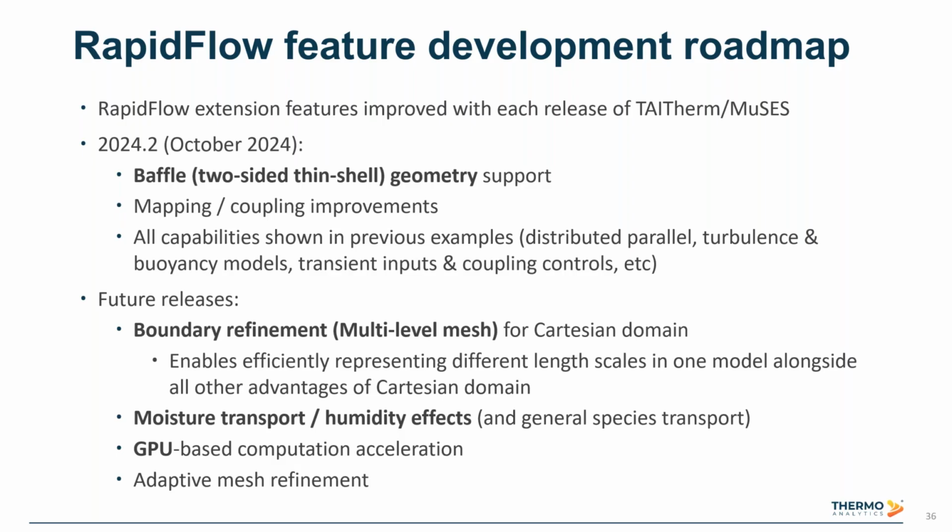So especially for cabin, what that will enable quite a bit is, again, the ability to more efficiently set up cabin cases where it's not just the flow from the vents into the cabin, but the flow, including perhaps the full HVAC ductwork and register louver geometry and details like that.